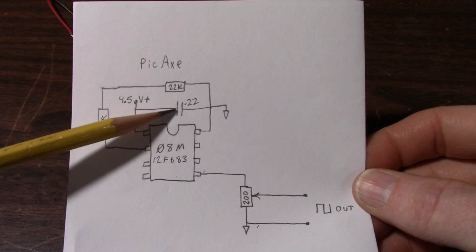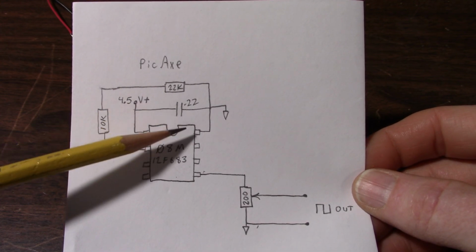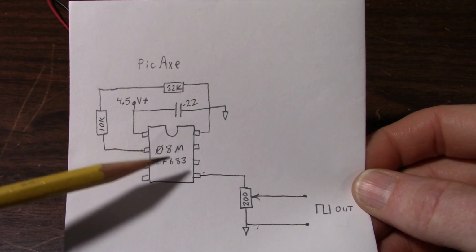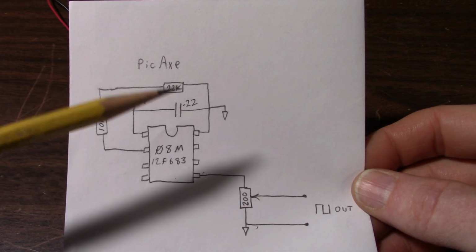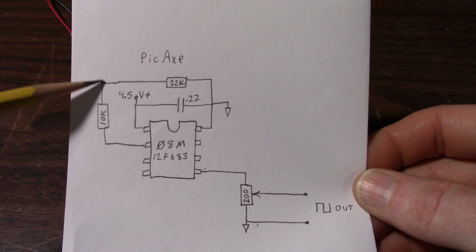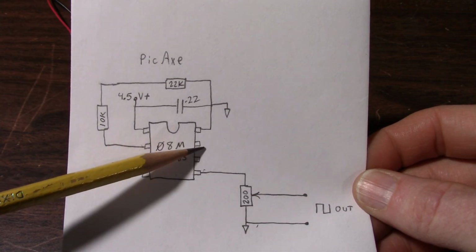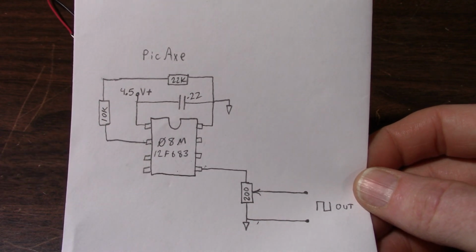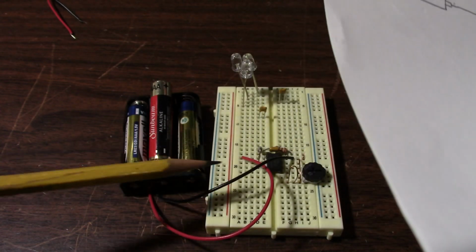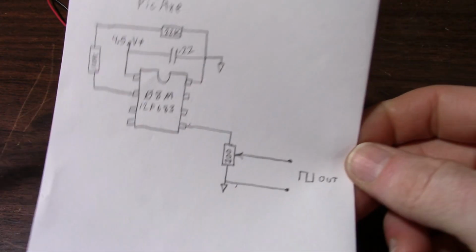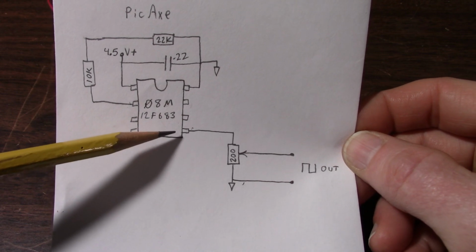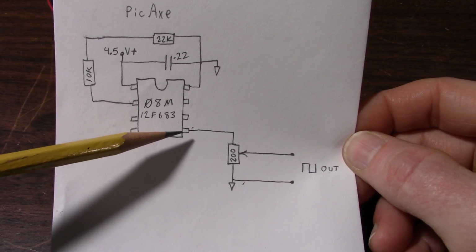That's just a supply bypass capacitor, and these resistors are connected in this way to keep the chip in run mode. Plus I can hook some wires up to the serial port on the computer, connect one here, and then one to ground, and program the chip. I can do it right on the board. I don't have to use a special programming board. But the main thing I'm concerned with is pin 5 here.